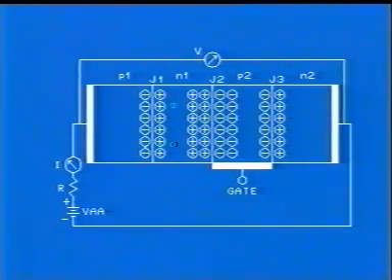One may recombine with an electron in N1 region. Hole being a minority carrier in N1 crosses over J2 and reaches P2 region. On reaching P2, it temporarily increases the bias on J3. This causes two electrons to cross over from N2 to P2. Again, one may recombine and the other being a minority carrier crosses over to N1.